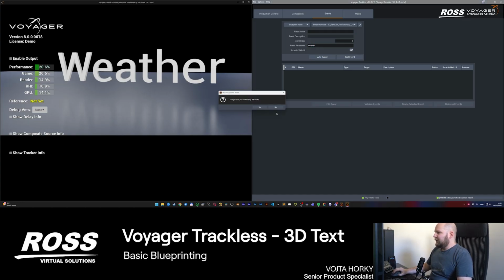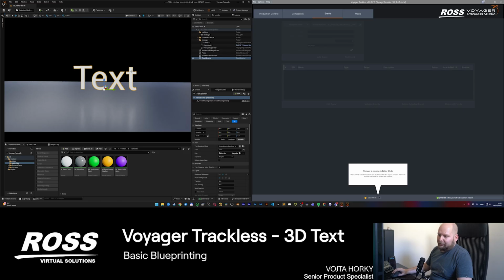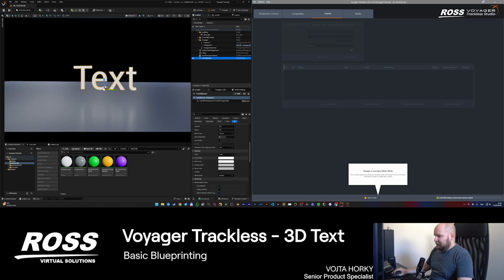I can do even more complex things. So let's say we want to even change the material or the color of the text. In order to do that, you need to go and set up something within the text actor. So if I select the text actor here in the details panels, I can see the material here.